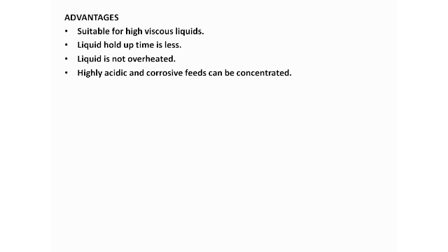Advantage: it is suitable for high viscous liquid, the falling film. Next, the liquid hold up time is very less here, as the liquid will move very fast by virtue of gravitational force, right. The liquid is not overheated in this method. Highly acidic and corrosive feeds can be concentrated here. It means you can concentrate acidic solution and corrosive liquid solution.